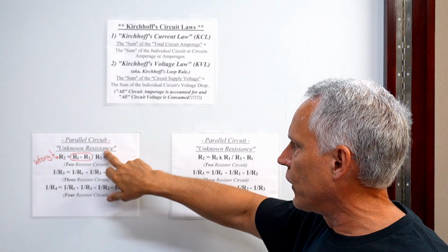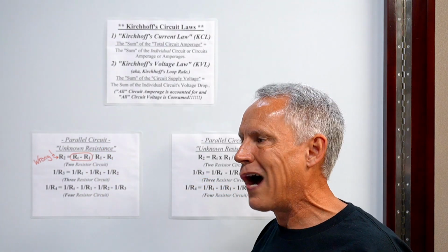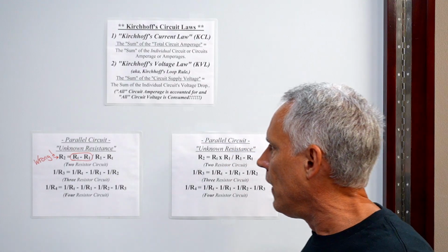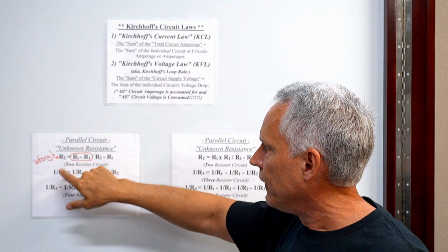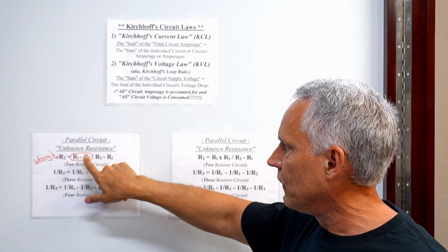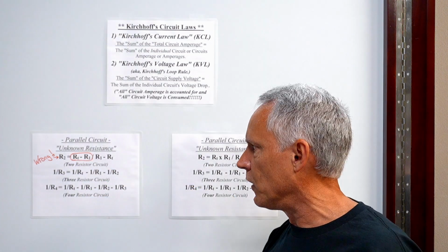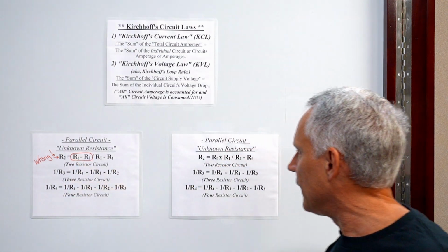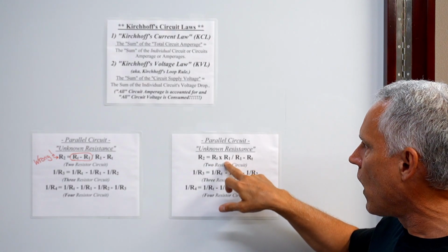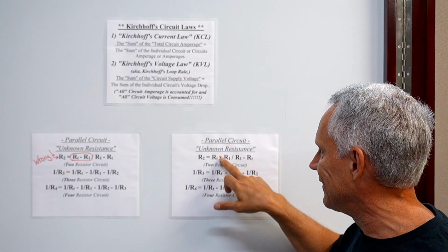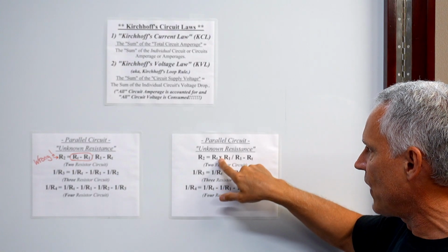I was showing the parallel circuit unknown resistance calculations, calculating for an unknown resistance. In the 2 resistor circuit calculation, I had put the resistance total minus the first resistance, or resistor number 1. The reality is that it should be resistance total multiplied by resistance 1, not minus or plus or anything like that, a multiplication factor.